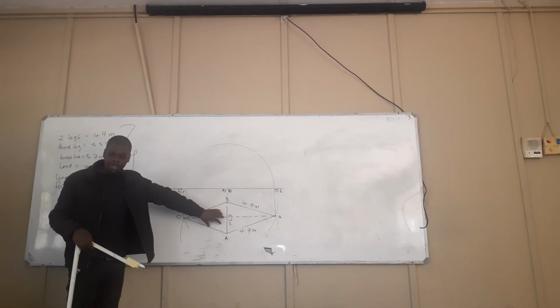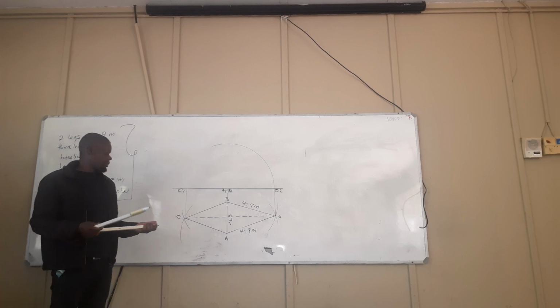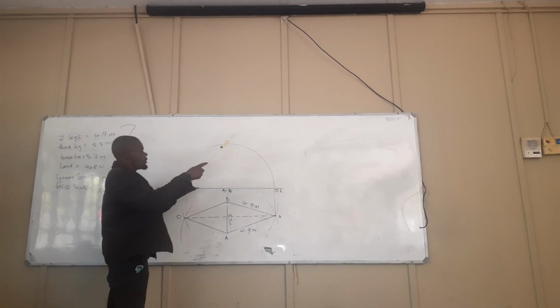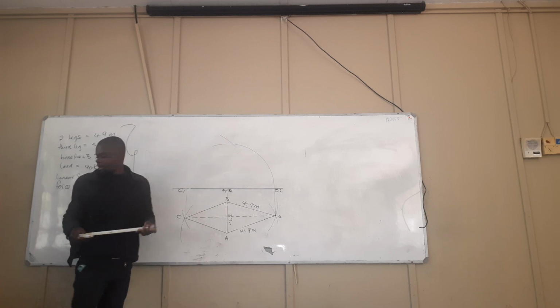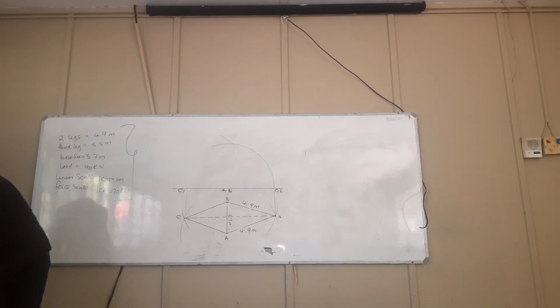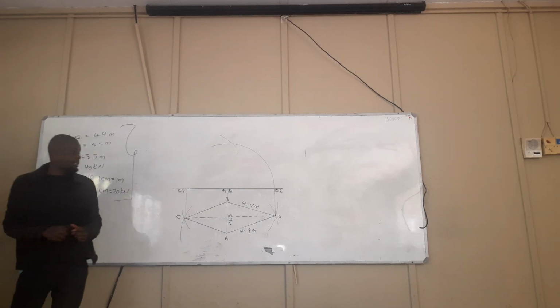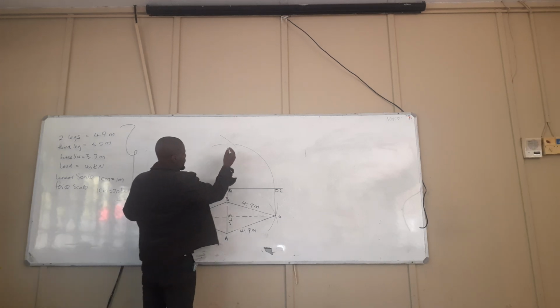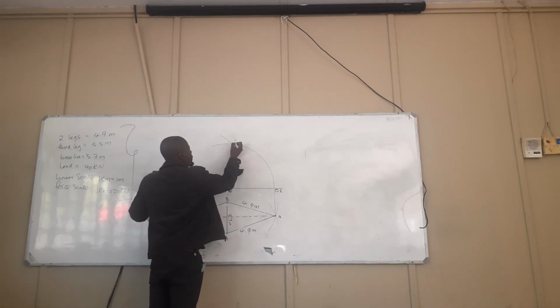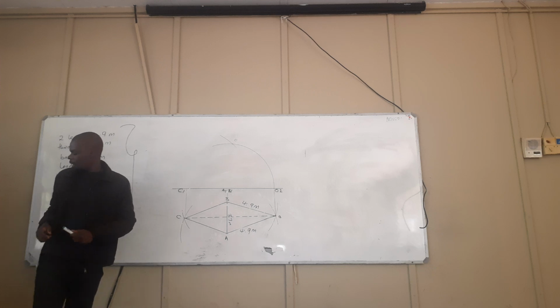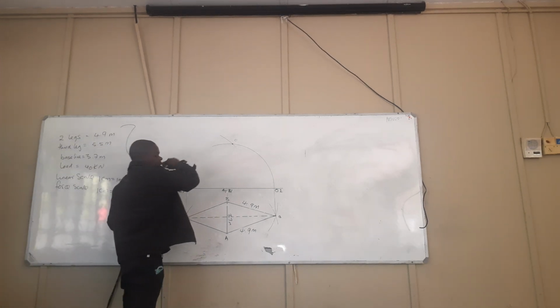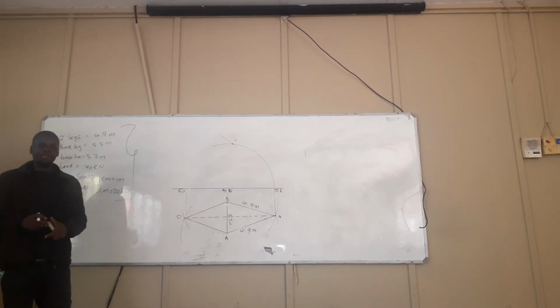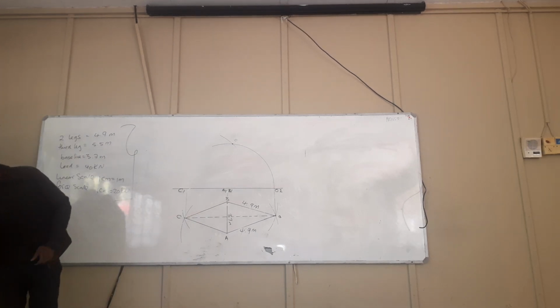Don't forget, this is the base that is being formed. All right, so with point C1 and your radius 5.5, subscribe an arc, and you're going to get point O. Point O is the apex of our tripod. That's where we are going to connect our chain block, which is the lifting mechanism that we are going to use.